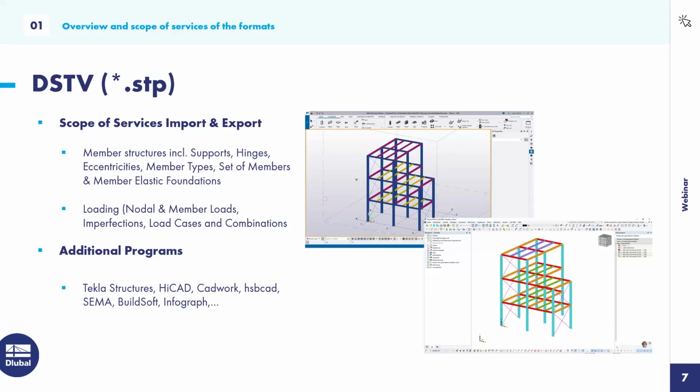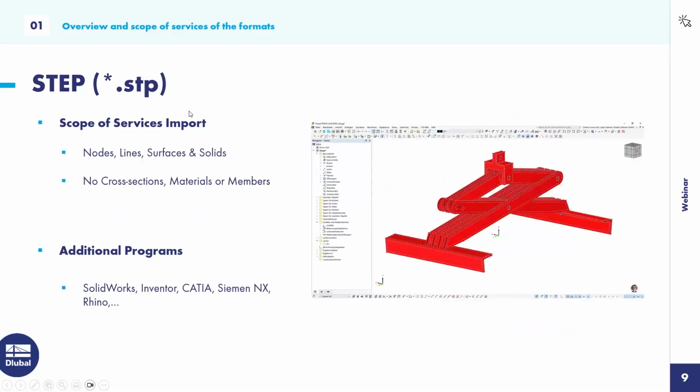So they couldn't be more different, beam structures versus solid models. Sadly, they use the same file format ending, which is causing confusions, because often we have customers reporting that the step import isn't working, but then they got a DSTV file or the other way around. So make sure to check out which file format really has been exported from another software,